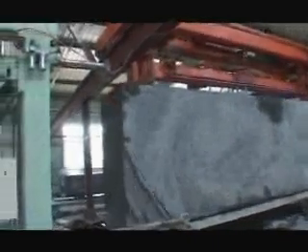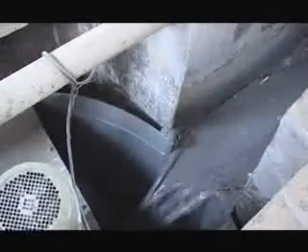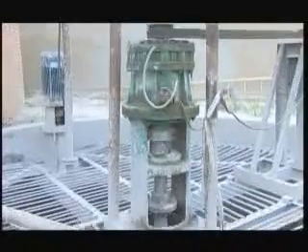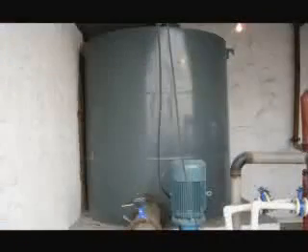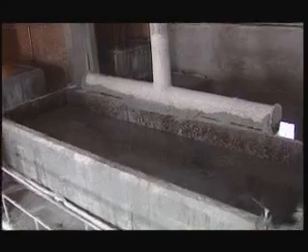While pouring and cutting, the recycling systems wash the waste slurry again and again, and the wash slurry pours into the recycling system. With constant mixing, the waste slurry reaches a certain concentration, and then is pumped into the waste slurry storage tank of the dosing process, for use by the slurry pump in the waste slurry tank. When the dosing of finished slurry is being done, the waste slurry is added according to a certain proportion for recycle.